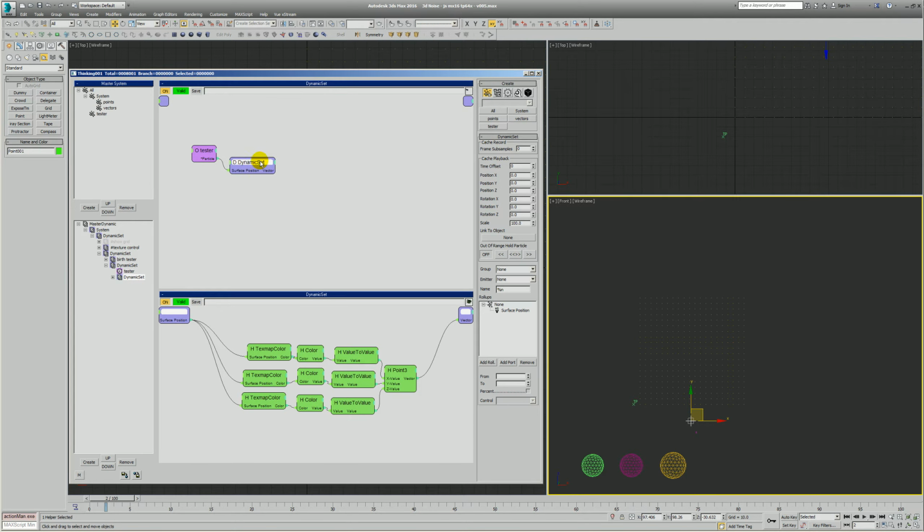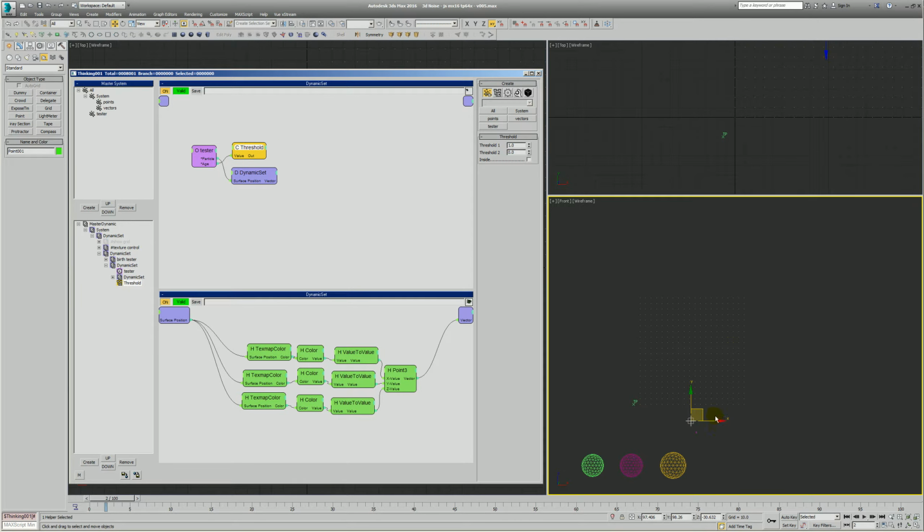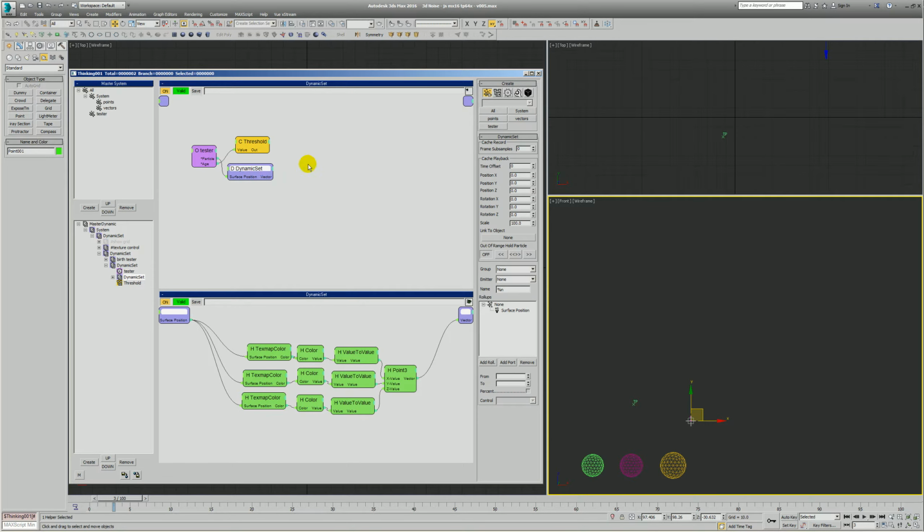So what we're going to do is have this particle look at its age, and if its age is over 10 or something, we're going to have it be affected by the noise. Remember, the points aren't there anymore. The noise field exists in space completely. So we'll have it begin to be affected, say, after age 20. So they'll fly straight for a while, and then they're going to get some vector direction.